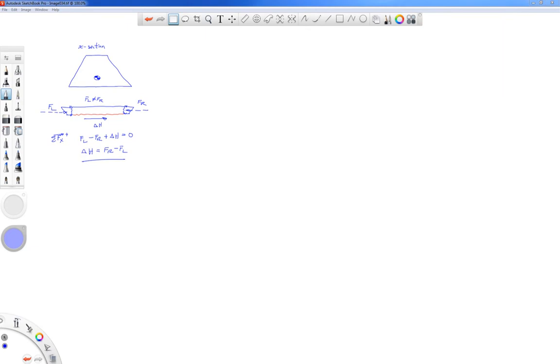Now, if you remember, again, the resultant force is the volume of the stress distribution. In this case, the resultant bending force on this piece of the free body diagram of the beam is going to be the volume of that shape. It's kind of a cut-off wedge shape. It's a trapezoid on the side view, but it goes through the thickness of the beam.